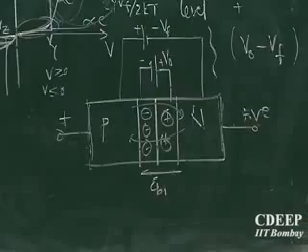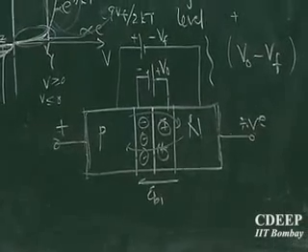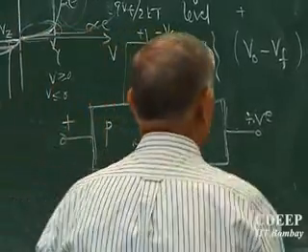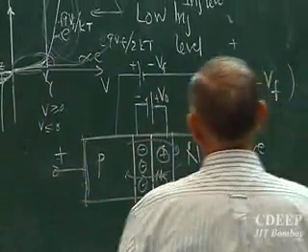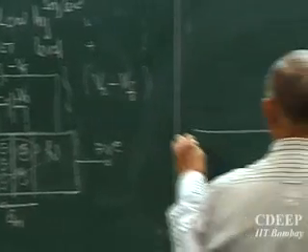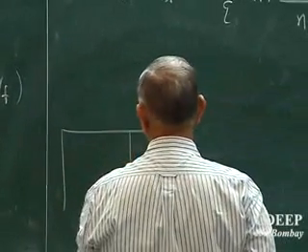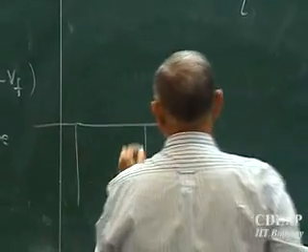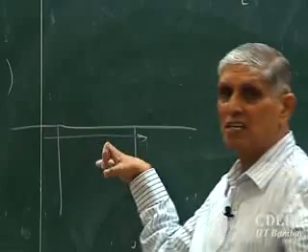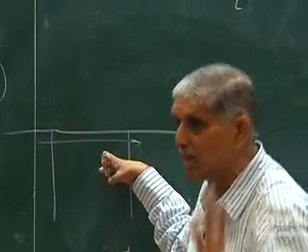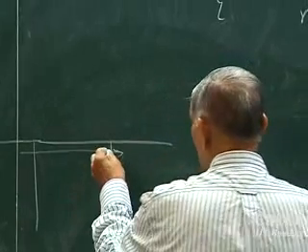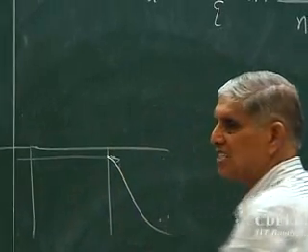This means there will be a current flowing in the PN junction. Is that clear? Now this current is what we call diffusion current. If I look at this depletion region a little more closely, on this side, let's say, the holes which are coming here, as I said, no carriers recombine in the depletion region. I said it, everything is free for that. As soon as they reach the edge, they start decaying.